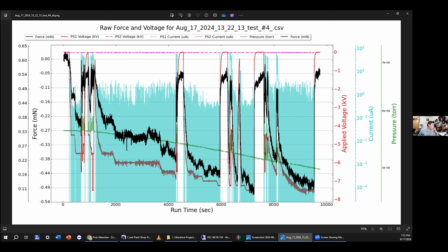I was pumping in somewhere around 1.8 milliwatts. That's about how much power is coming out of my high voltage power supply, passing through a 100 megaohm resistor so I don't short anything out. The system eats about 1.82 milliwatts just to run. Not all of that is used to produce thrust; probably 99% of it is producing heat in the 100 megaohm resistor. I just want you to see that the test as a whole went exactly the way all the other thousands of times I've done this test.